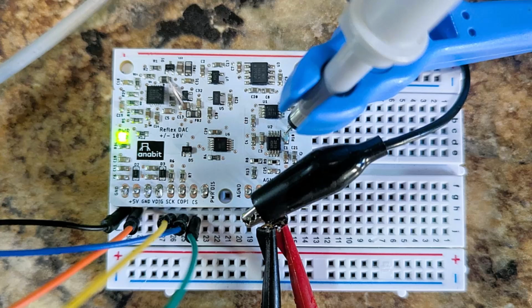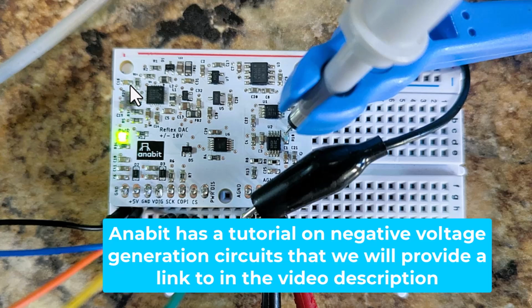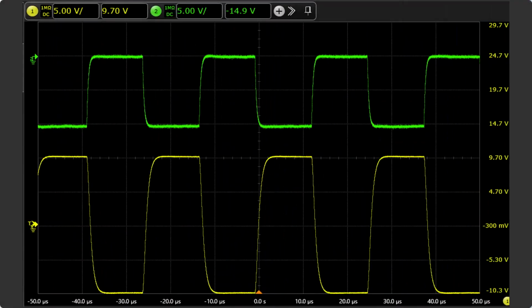And then of course, one of the more important things, and one of the harder to design things, is this DC to DC converter that's a dual output. It takes a 5-volt power in and creates a plus 15 volt rail and a negative 15 volt rail for our op amp, so we know that we can get that full range of plus and minus 10 volts on the output. All right, here's a screenshot from my oscilloscope.